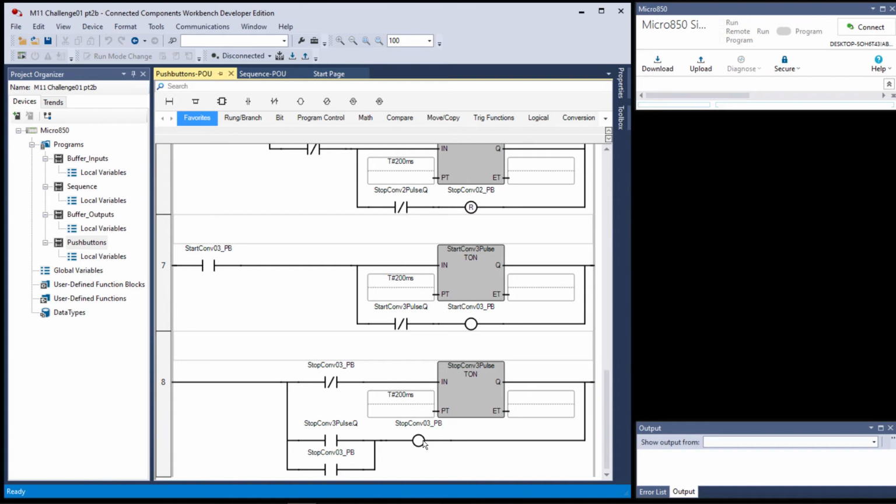In this logic, an OTE, a direct coil, has a true and a false execution. It executes every single program scan, so 3,000 times a second at a minimum, this instruction either tells that bit it's on or it's off. That would be like you walking by a light switch on the wall, a toggle switch, a wall plate. And every time you walk by it, you swipe your hand over it.